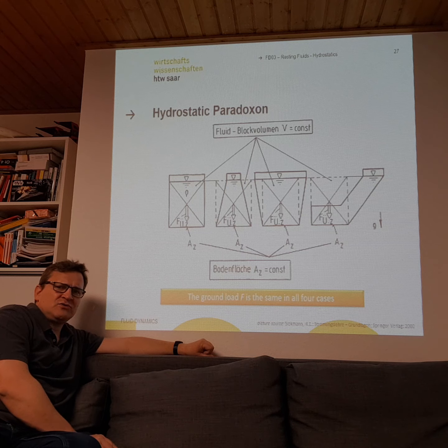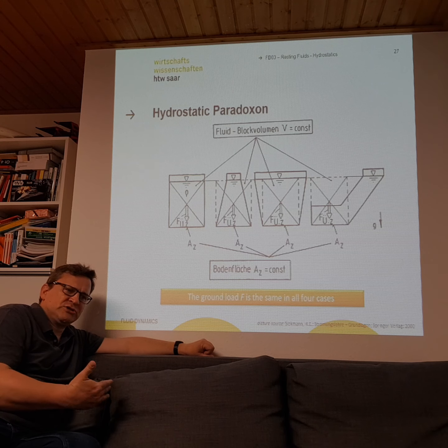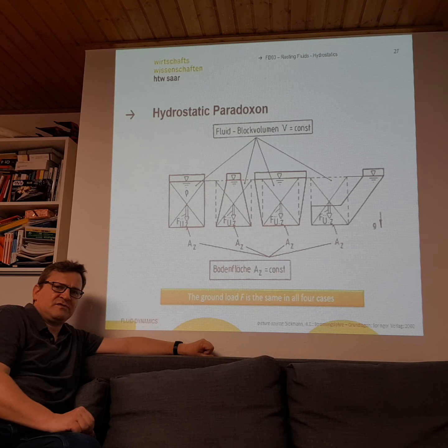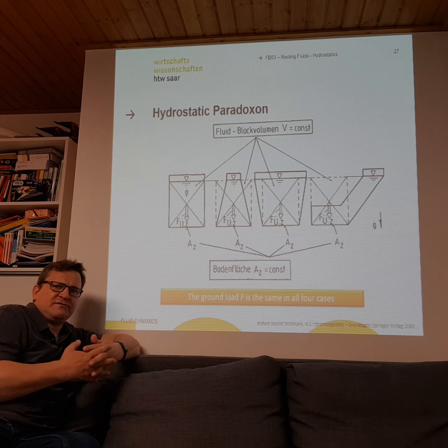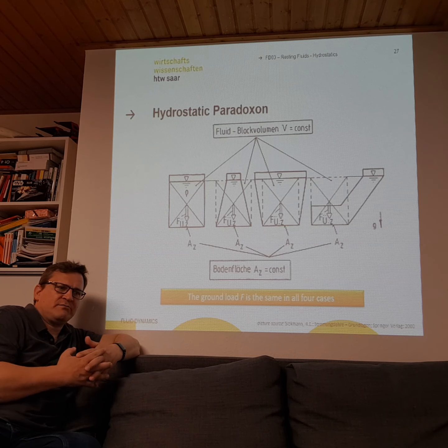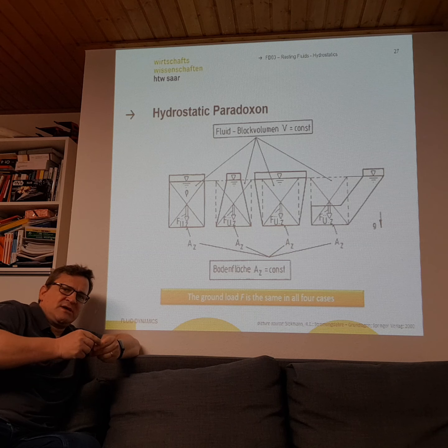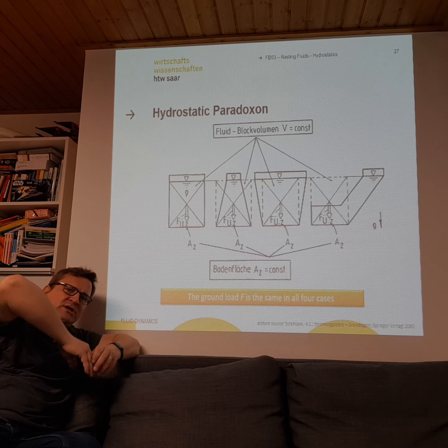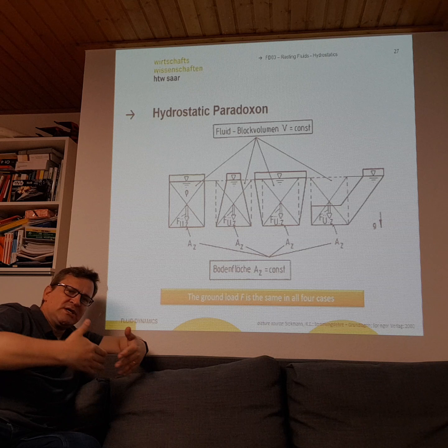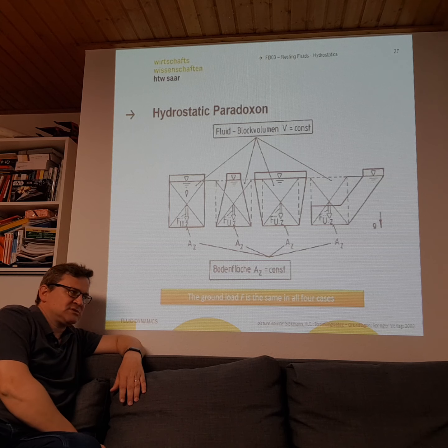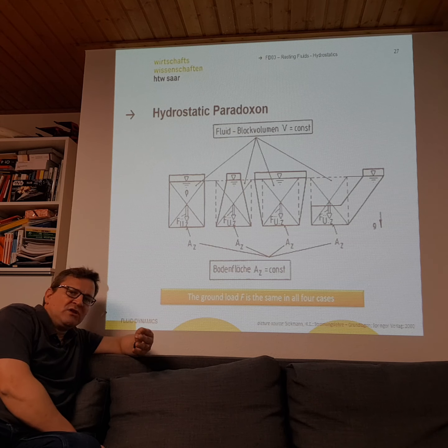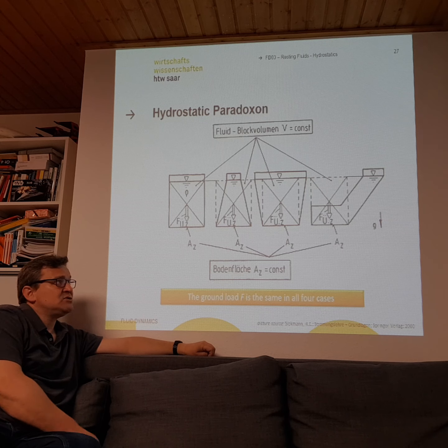And that's an effect you can also use to test the pressure inside big power plant vessel systems. If you want to look at how much pressure you can fill into a big tank of a power plant or so, you just make a small pipe, fill it with water, and then you will get really high pressures inside the pipe systems. Even if you don't have a lot of water, that's a fact you can use.